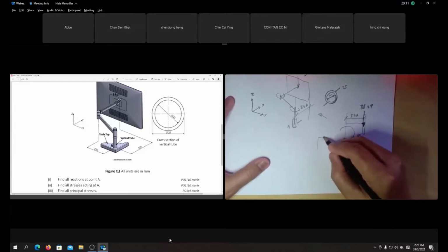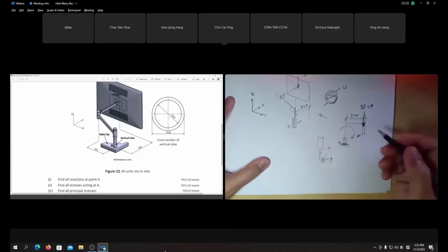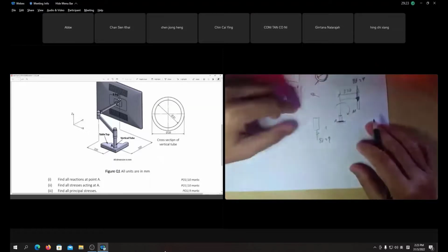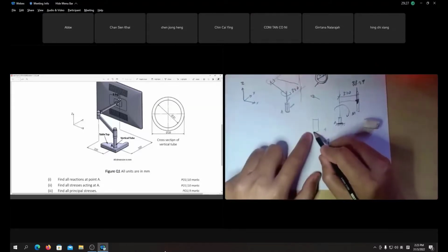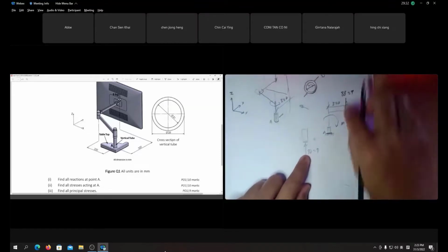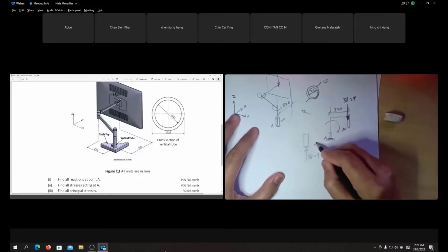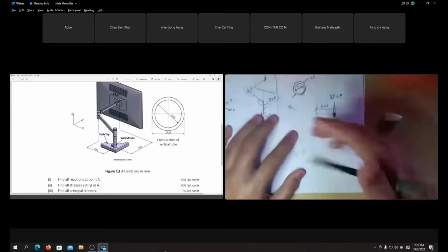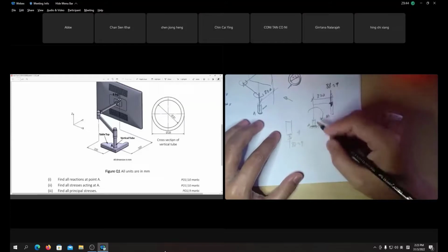Okay, kalau the way you put your free body diagram, you can do lah. This is my tube A, right? So reaction is like this lah. The same as 88.29, betul kan? Plus, since the bending is like this, my counterclockwise is like that lah. Tetapi tak apa, sometimes it's okay kalau you put the free body diagram like this. If I'm taking at the end A, the reaction should be 88.29 because this downward reaction, and this one moment is clockwise, and this one is counterclockwise. You can do that also.